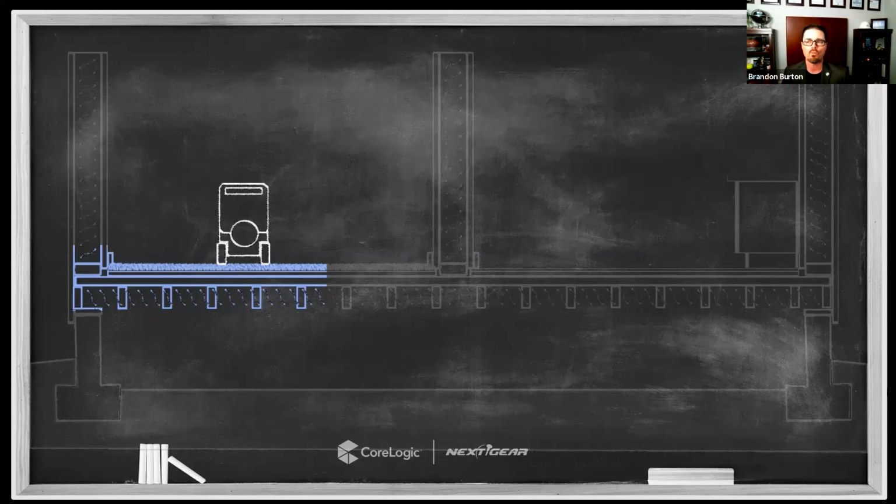The only way that warm, dry air is going to be of any use to us is if we place it into direct contact with the wet evaporating surfaces. And this is where air movement becomes key, right? We install these air movers so that we can draw that warm, dry air from the environment and then move it readily and rapidly immediately across that wet surface.